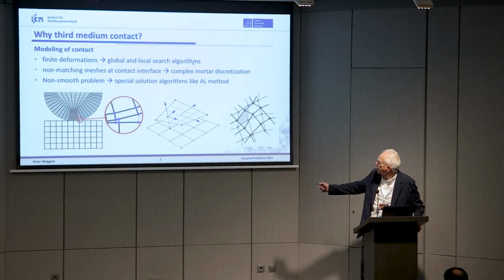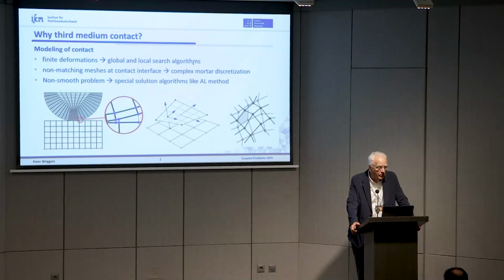You have non-matching meshes, and classically what we do is we use mortar methods. It looks like this, which is also not so easy. And actually the contact problem is a non-smooth problem, which means that you need very special algorithms like the augmented Lagrangian schemes and other things more. So you have to do a lot of things for contact mechanics. Nowadays, of course, there are a lot of commercial programs which work, and I don't want to say that you have to do a lot of research in this area, but in the background it is quite complex.